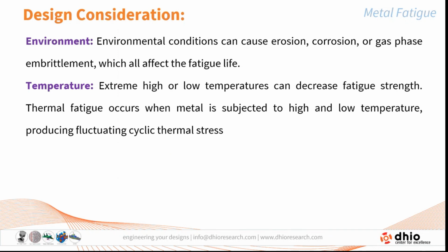And also in the design consideration, one has to look at the environmental conditions which cause corrosion, erosion, or embrittlement, which have an effect on the fatigue life. Then again, the temperature of the working environment, because extreme high or low temperature can decrease the fatigue strength. As we all know, thermal fatigue occurs when the metal is subjected to high or low temperature variation. There is a fluctuation in the temperature, usually called thermal loading, and that is called thermal fatigue. These thermal fatigue conditions have an effect on the fatigue life of the component.